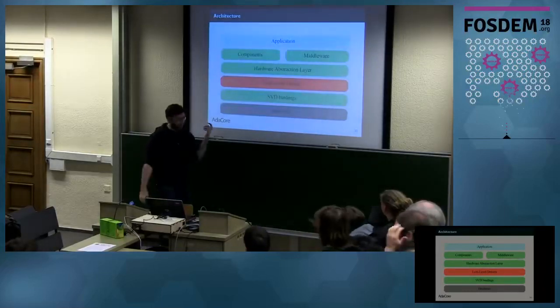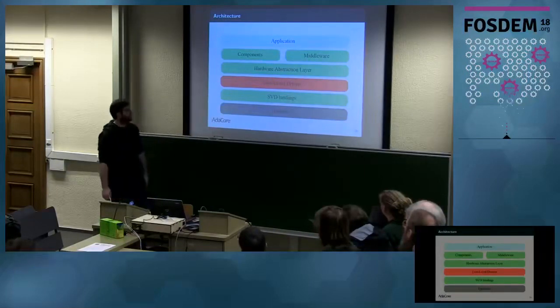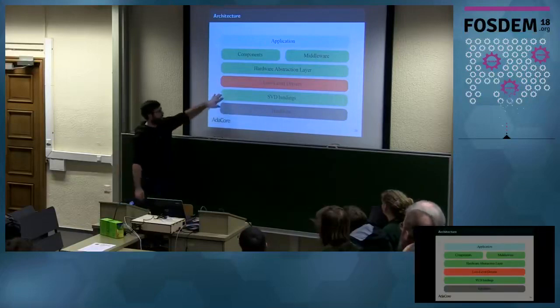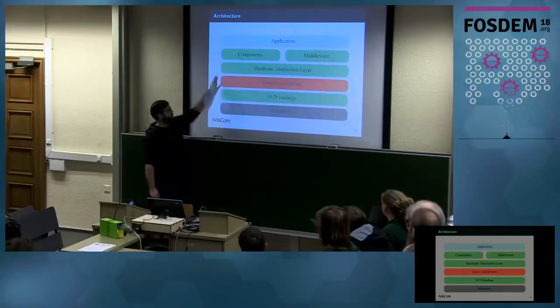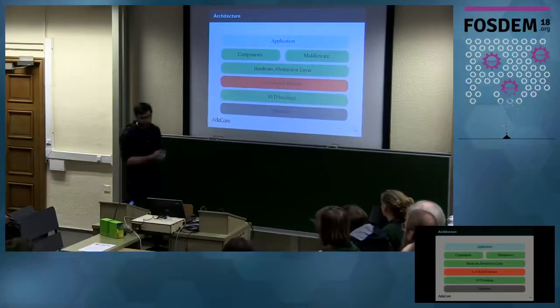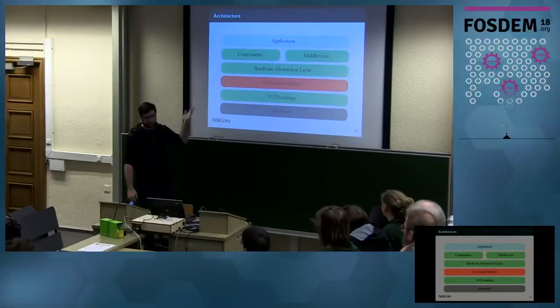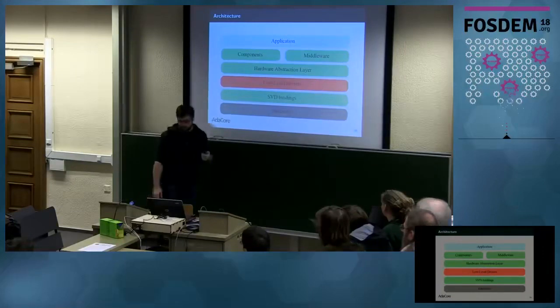So this is more or less what it looks like. You've probably seen this kind of diagram tons of times. What's important to see here is that this part, the SVD binding, is generated by a tool. This part over here, the hardware abstraction layer, the components, the middleware, are all portable. So really, if you want to benefit from the Ada Drivers Library, and if you want to start programming your microcontroller in Ada, you will have to focus only on these low-level driver parts, if you are using a microcontroller that we don't already support, of course.